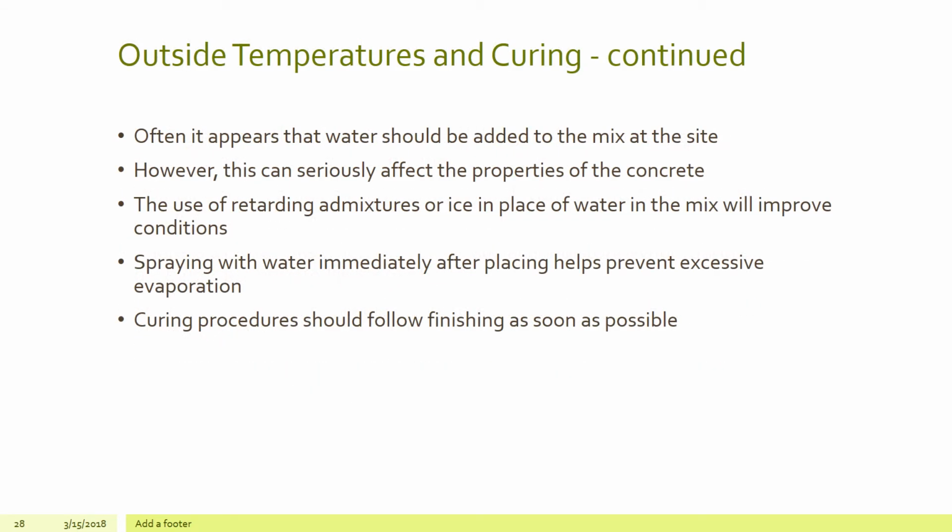Often it appears that water should be added to the mix at the site. However, this can seriously affect the properties of the concrete. The use of retarding agents or admixtures, or ice in place of water in the mix, will improve conditions. Spraying with water immediately after placing helps prevent excessive evaporation. Curing procedures should follow finishing as soon as possible.